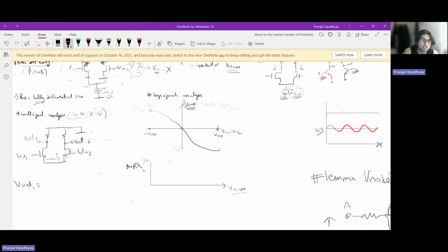Assuming that this circuit is symmetrical and these two transistor sizes gms are equal, we can just directly write from the formula of a degenerated CS stage, which is given by gm times R, if I'm saying the resistor values are R, over 1/gm plus 1/gm, where 1/gm is the resistance seen from the source of this guy, right? And I'll just multiply it by Vin1.